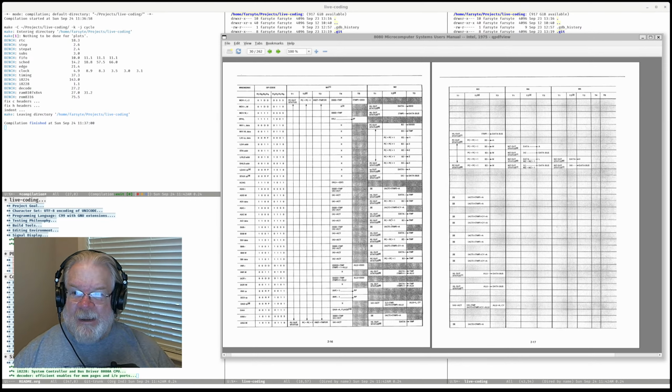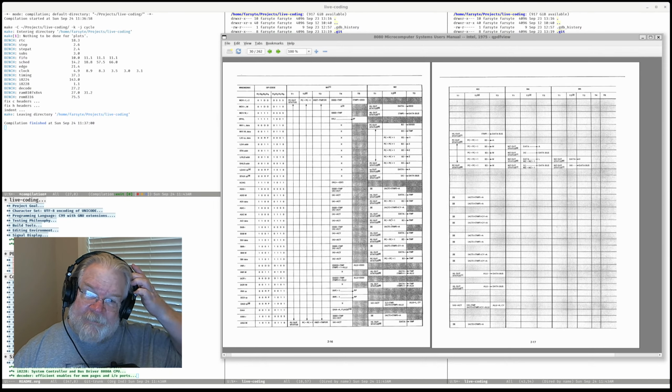And we can see here on this diagram, which it occurred to me today, that this could have been microcoded. So I could have analyzed all of these and designed an appropriate, very long data word microcode. That would be hardware engineering techniques from the late 80s, early 90s. Our address decode would basically be given the instruction, we would then set up this VLIW thing, which would then have a bunch of signals out, each one of which would drive a behavior. But not doing that. Instead, I'm using the instruction to select a function.